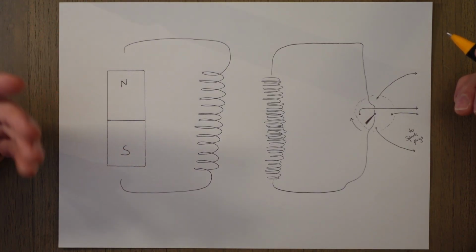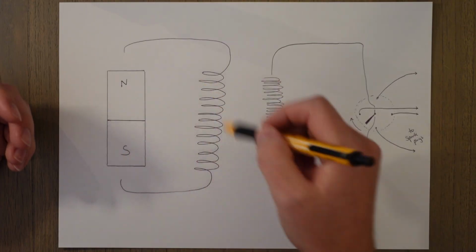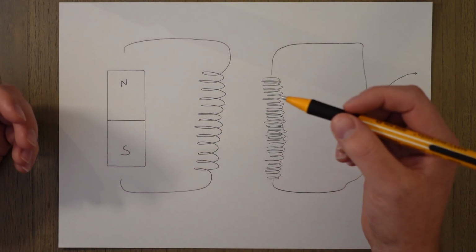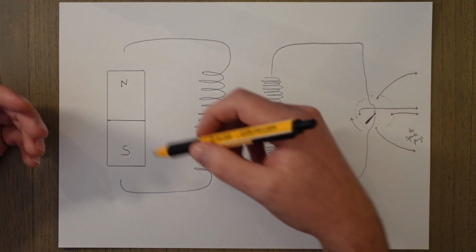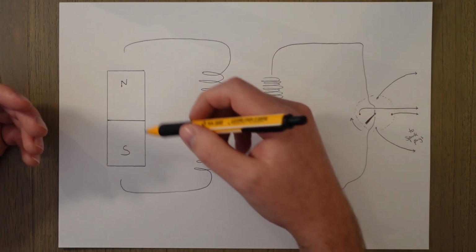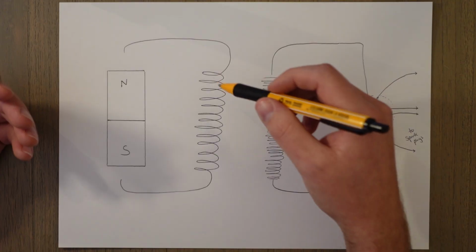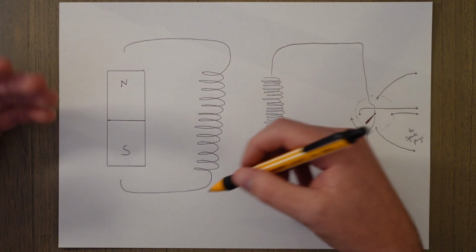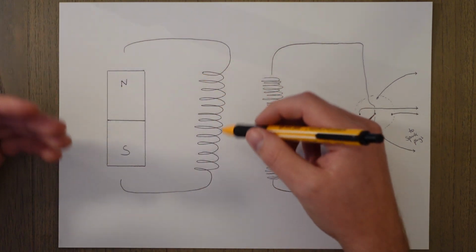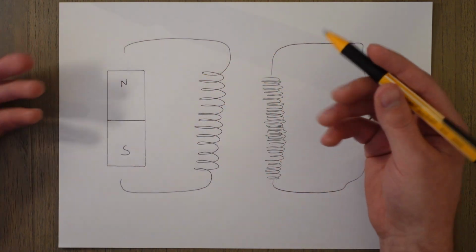We can also achieve the same effect by just rotating a magnet near a coil of wire, and the magnetic field will spin and pass over the length of wire, pushing the little electrons along, and as the other side of the magnetic field passes over the coil, then they will pull the electrons back along and the current will flow the other way, again producing AC electricity.